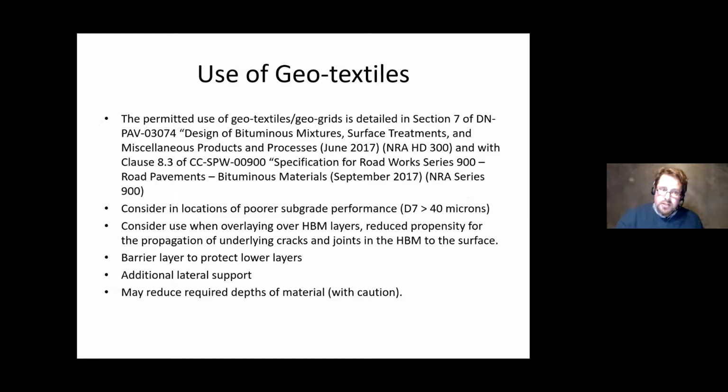So the usage of geotextiles, again, can be quite controversial, but the usage of geotextiles is permitted, and the reasons why it's permitted are detailed in Section 7 of HD 300. And there's also specifications on them in Series 900. They're excellent in locations of poor subgrade performance. I've referenced 40 microns there, but that's when you want to start considering it. If you're looking at a D7 greater than 50 microns, you really want to be using it.